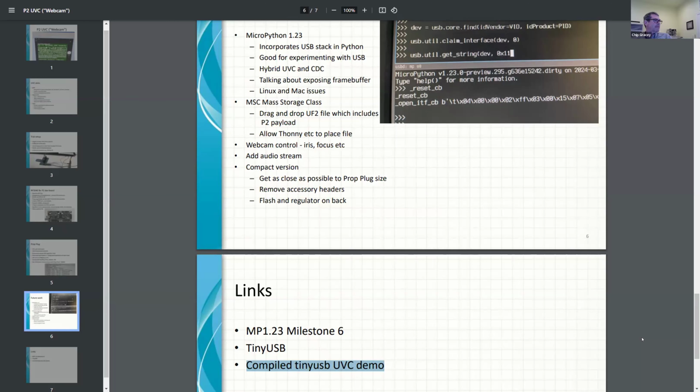Got it. Okay. And it must have USB 2.0, right? I mean, because of when it was built. Yep. Well, I believe with TinyUSB there's a matrix which shows on which processor it runs at 1.1 versus 2, and I think for the RP2040 it just shows it using USB 1.1. I don't know if that's still current or up to date. It's consistent: if we're finding that the limitation is sending video in at 6 megabits per second, and USB 1.1 is 12 megabits per second, it probably makes sense that this is where the bottleneck is at the moment.